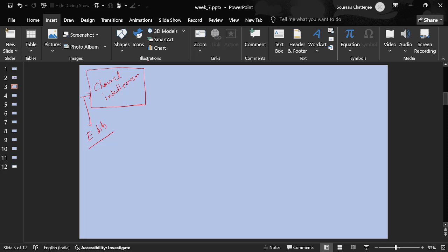So the channel interleaving principle is something like this. You can draw an isosceles triangle kind of thing. It's good for the visual interpretation of how it happens. Basically, what I'm planning to do, I have these E bits, a sequence of length E. I will write those bits in this order. I will fill up the first row like this, and then I will start writing from the second row, and I will keep writing that onwards.